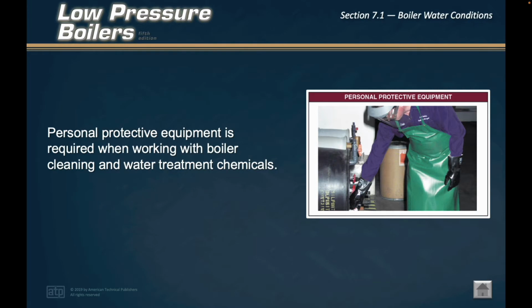Rainwater accumulates chemicals, gases, and particles as it falls to the ground. Standing water accumulates solid and gaseous pollutants on its surface. Groundwater contains dissolved solids from the minerals and dissolved gases. Dissolved solids are impurities such as calcium, silica, and iron that have dissolved into solution. Drinking water, also known as potable water, also requires removal of solids and gases before use in the boiler.